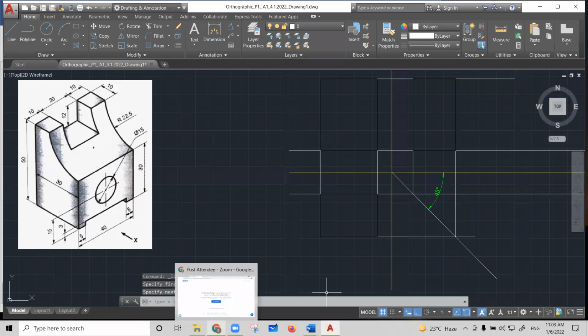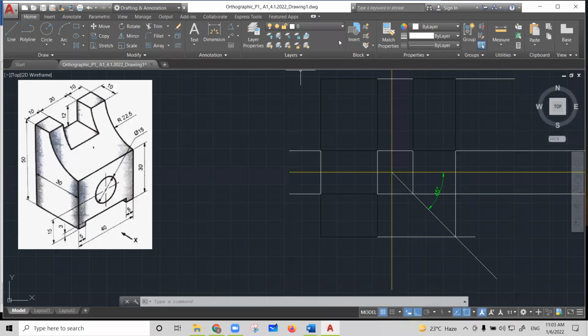Okay, so height is 50, length is 40 millimeter, width 30 millimeter. Then see, you have to add the surfaces visible to you. When you are looking from this end, this 5 millimeter edge is visible. Then height by 3 millimeter vertical one, and then completely this edge of 30 millimeter height is visible to you. As well as when looking from this end, this curved surface is also seen as a straight line for this edge. Whatever the curve or straight one, they are going to be visible from front view along with this circle.